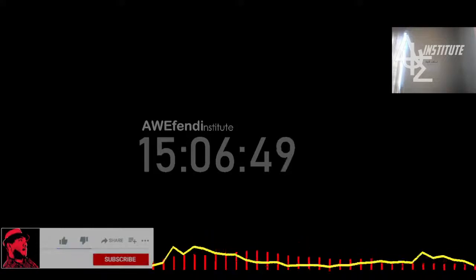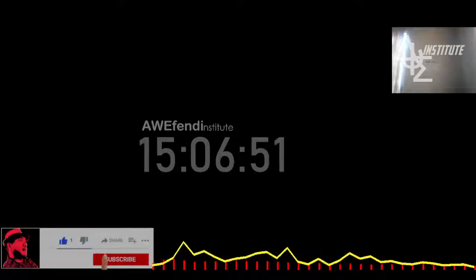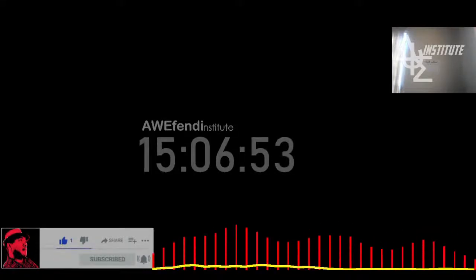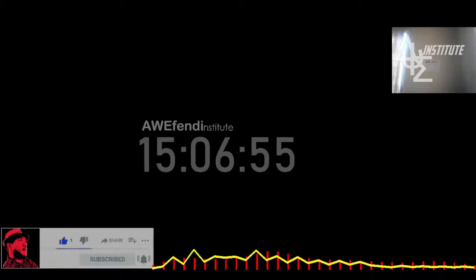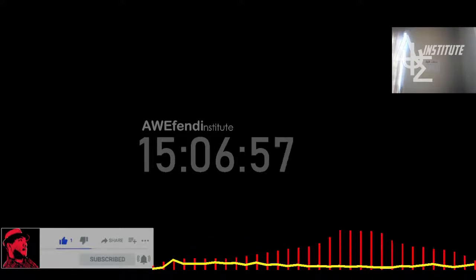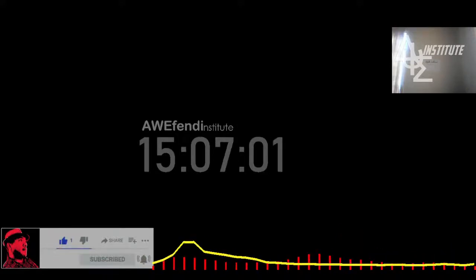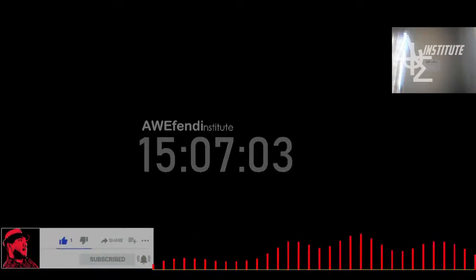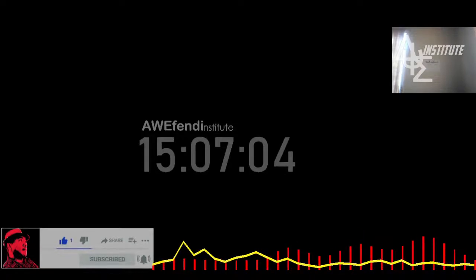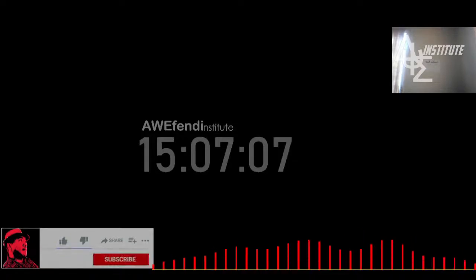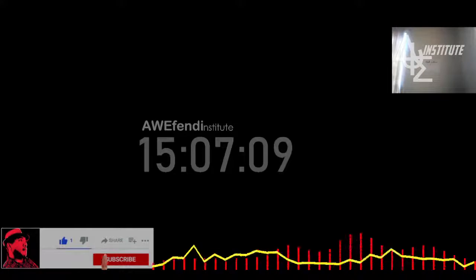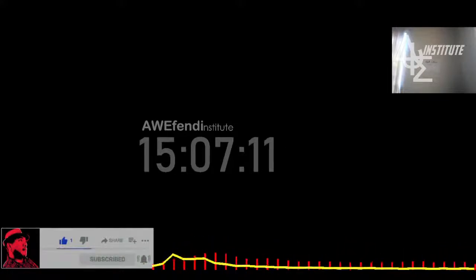So what I'm going to do is set up a monitor on this outlet, and we can set up velocity, for example. Then we can rename this to average velocity outlet. And you can see that the value pops up on your screen.